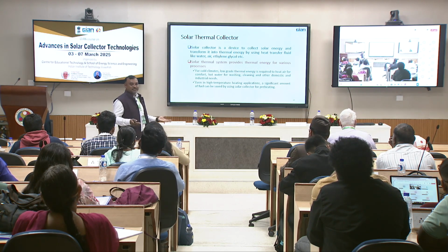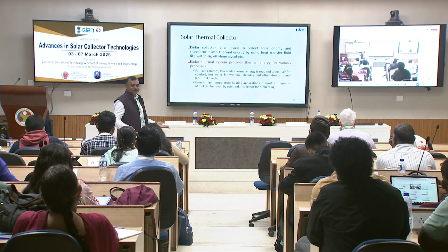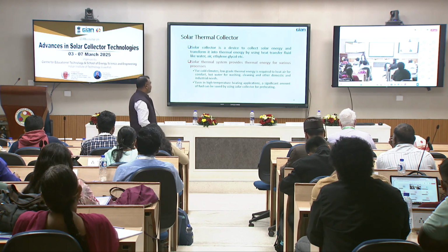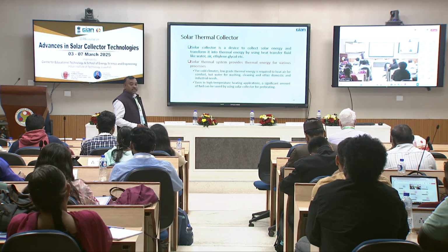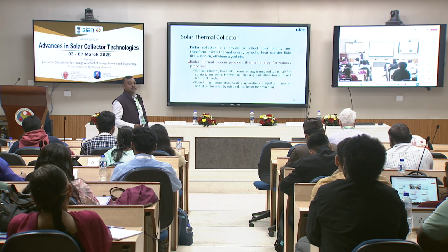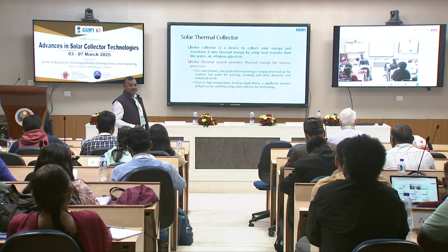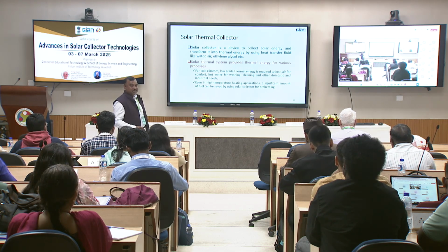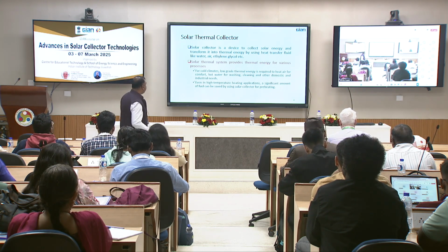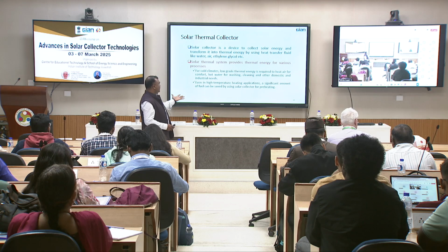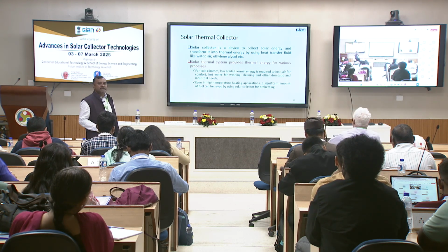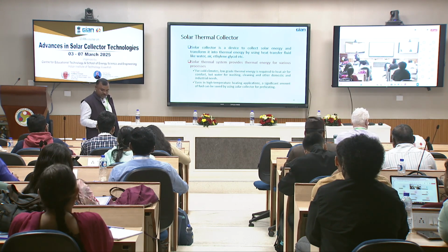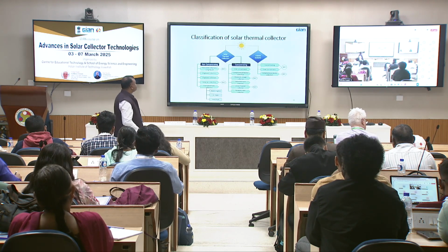But mostly we are below the 500 level, so we don't need that much heating, but we need cooling. That's why we are stressing more on vapor absorption refrigeration systems. Can we have a low cost vapor absorption refrigeration system? Can we have a solar assisted dehumidifier? These are requirements for us. Even in high temperature heating applications, a significant amount of fuel can be saved by using solar collector preheating. So these are primary applications across the globe.